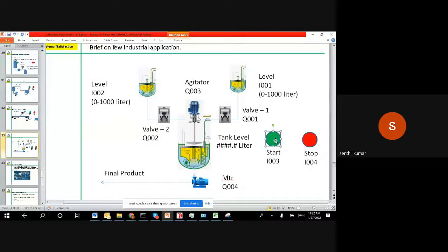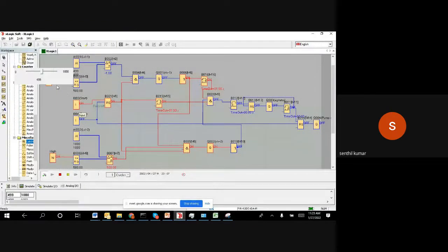Now, since the second valve is open, as we said, when you push and release, we want to open this valve, and then from the tank, if it goes less than 500 liters into the reactor, you want to close this valve. After closing this valve, you want to open this valve immediately. That's what we tested. That's what worked so far. So once this is opened, this liquid will start dropping because the liquid from here will go inside the reactor. So let us simulate this value.